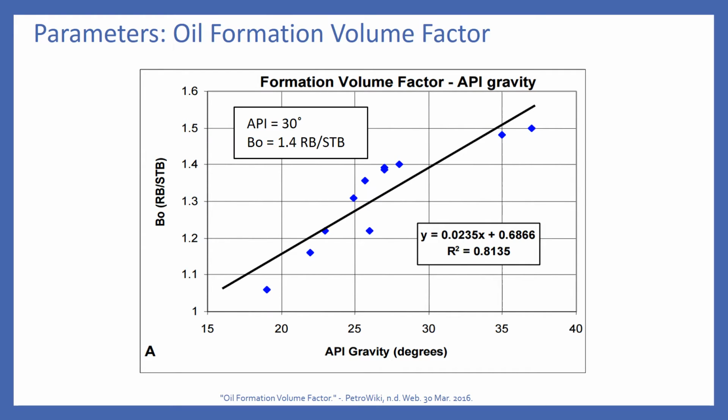Our given API gravity of 30 degrees API allowed us to obtain a formation volume factor for oil of 1.4 using this curve fit of formation volume factors with respect to API gravity.